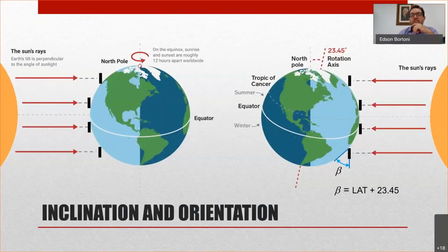The right inclination is very important because the important thing is to have the sun rays orthogonal with the normal of the plate. So it varies along the position. If you are here, the solar plates may stay at 90 degrees, and if you are exactly here, the solar plates may be at 0 degrees to the horizontal.